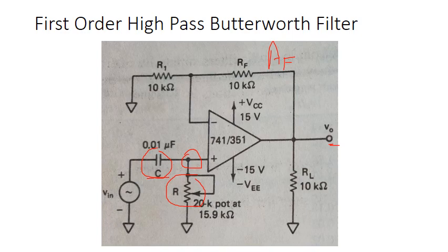So this is calculated by the voltage divider rule, which is Vin into R divided by minus JXC plus R. So this point we can take it as V1 is Vin into R divided by minus JXC plus R, and RL is the load resistance over here.